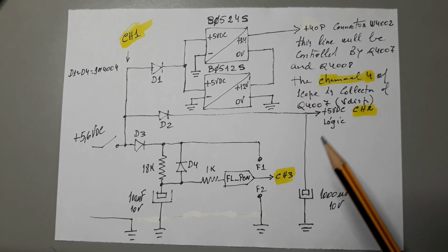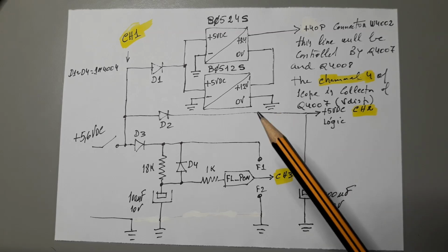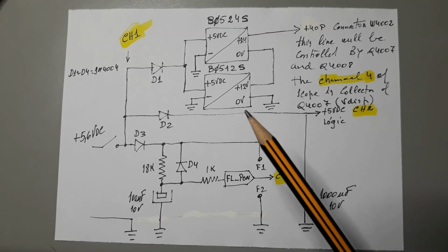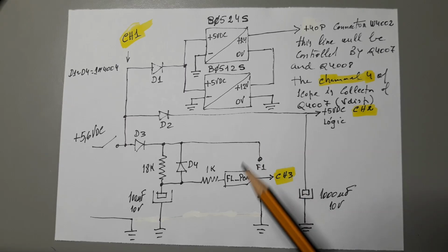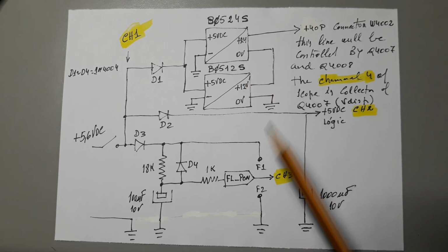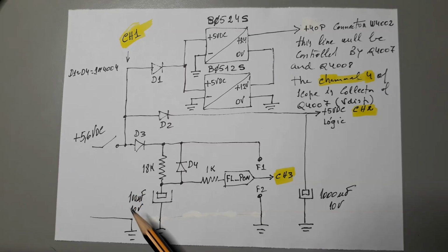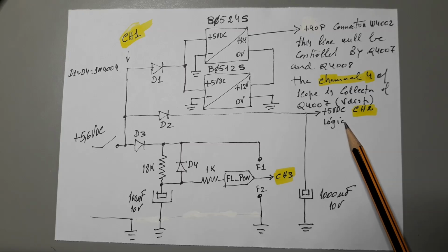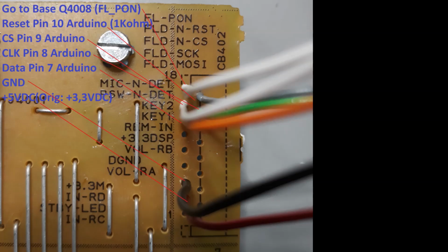Because the driver is a positive driver, we only need two levels of voltage. In this case, we have 36 volts to the grids and segments, and we have the 5 volts DC to the logic and to the filament. These are the connections necessary to bring the panel to life again.